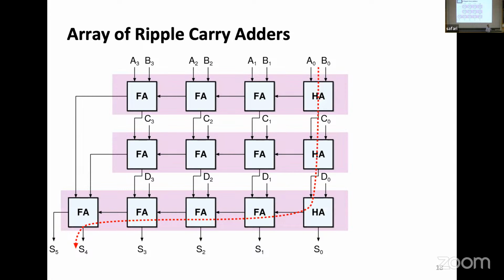Ripple carry adders are slow. Ripple carry adders have this very long propagation that goes through them. However, this slowness works in their advantage when you are adding multiple numbers. When you are adding multiple numbers, you can actually afford to do what I said, let's not do it. You can have the adder at the top adding the vector A3 and B3, A2, B2, A1, B1, A0, B0.